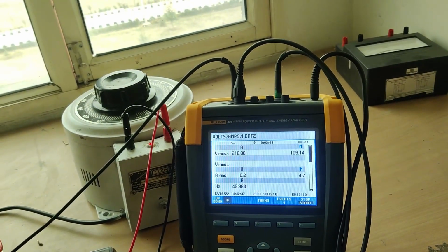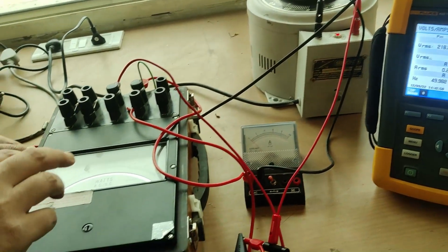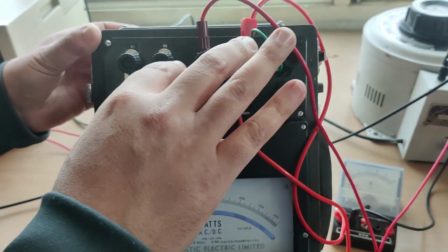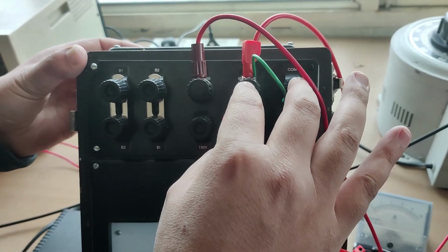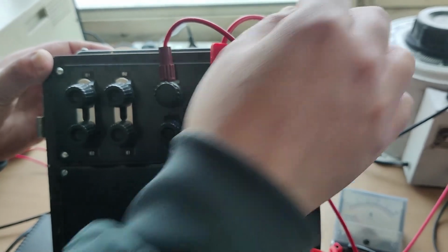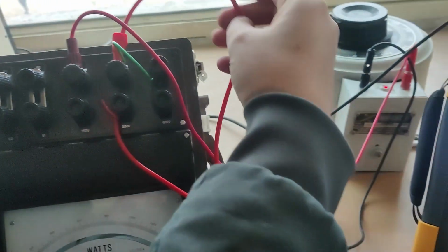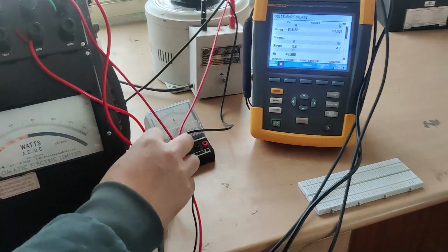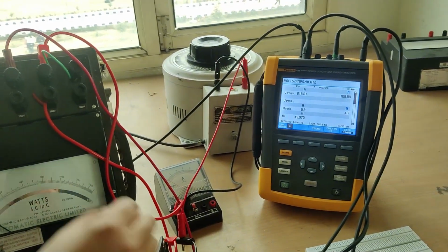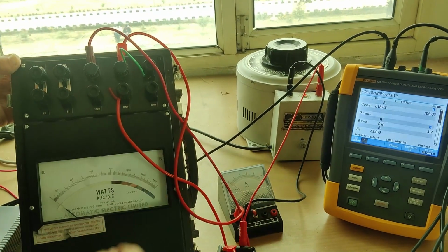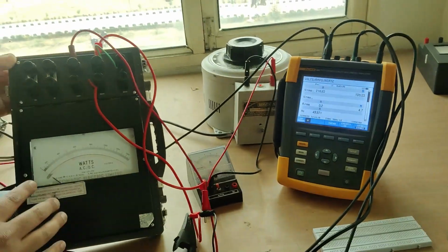Afterwards, you can see the wattmeter. We have 4 connections: M, L, C, and V. We have already given the connections here. This is M and C. As you already know from the circuit diagram, M and C are shorted. We have shorted them by this green wire. Then M goes to the mains through the ammeter. This is L, and it goes directly to the load. And then from V we have 2 connections. One goes to the input, that is here, and another goes to the load, that is here. So this is the wattmeter connection.